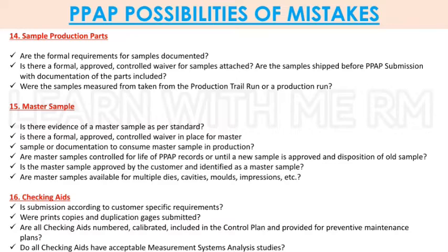14. Sample production parts. Are the formal requirements for samples documented? Is there a formal, approved, controlled waiver for samples attached? Are the samples shipped before PPAP submission with documentation of the parts included? Were the samples measured taken from the production trial run or a production run?